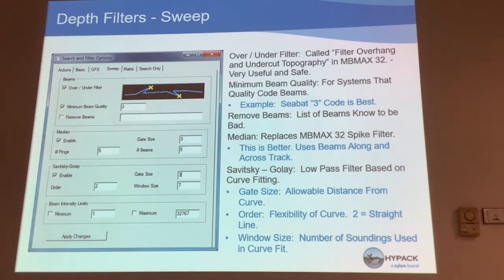It depends on whether you want to accept it or not. Sometimes, for example, when the beam goes into the water, it might spread too much, and then you don't actually get the bottom of the seabed because it's lost a lot of the intensity of the beam. When it comes back, it will send you a beam quality check, which you can use to see whether the multi-beam is giving you a high quality return or a low quality return.